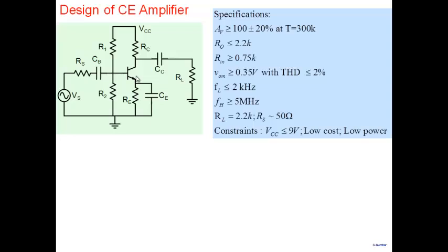From there you derive the specs of the A to D, and from there the specs of the big 4-stage amplifier, and eventually what the spec of this particular stage should be. So the blood pressure meter may have specs, but eventually you have to derive from there what the specs of my small stage should be. So it could be a standalone amplifier, or it could be a small part of a blood pressure meter. Depending on the overall system design, you derive these particular specs here.